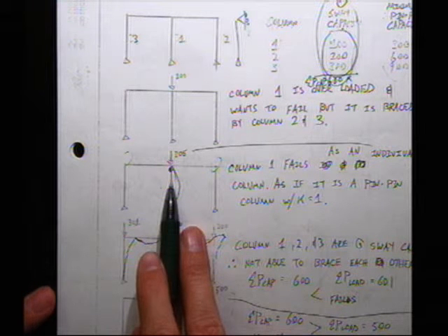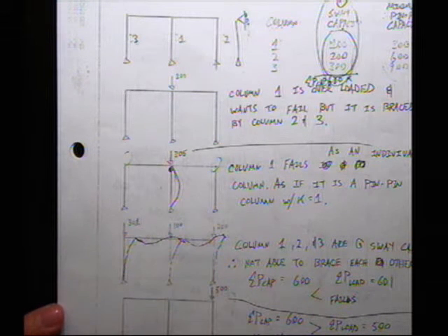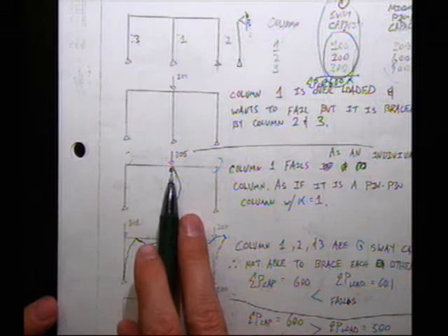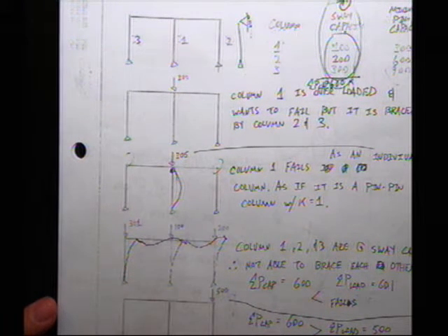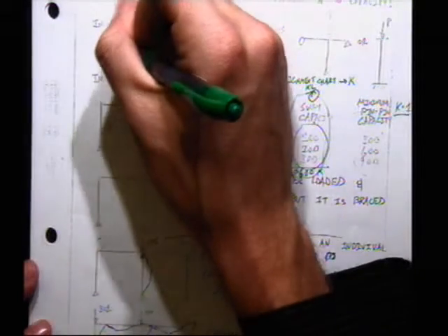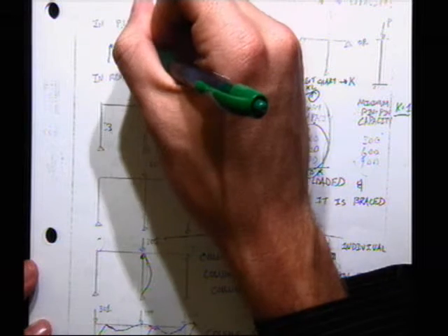But how are we going to work the problems? We're going to assume a K equal to 1. Why? Because it's a pain in the butt to do otherwise. This doesn't happen very often. This almost never happens. In a real structure, everything is pretty uniformly loaded, or somewhat evenly loaded, depending on its tributary area. And things don't usually fail as a pin-pin column. What usually rules the day, especially if you have frames with lots and lots of pins at the top.